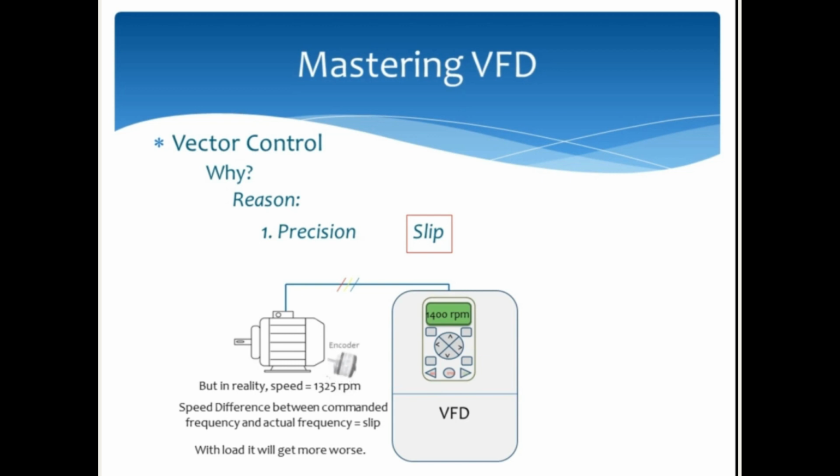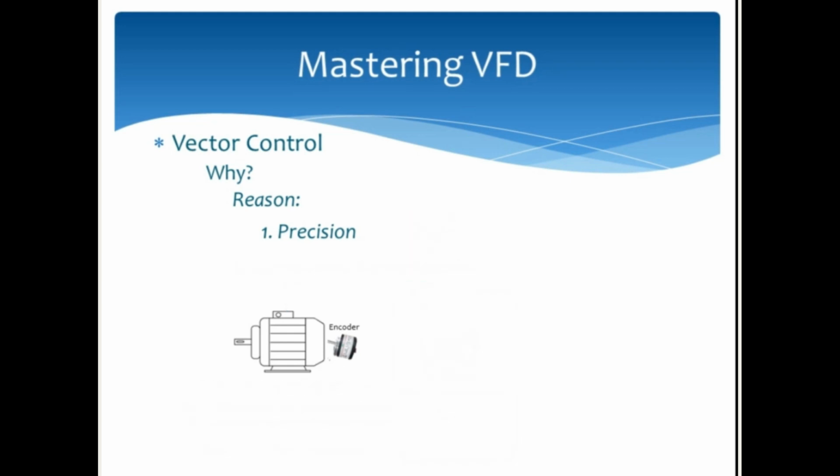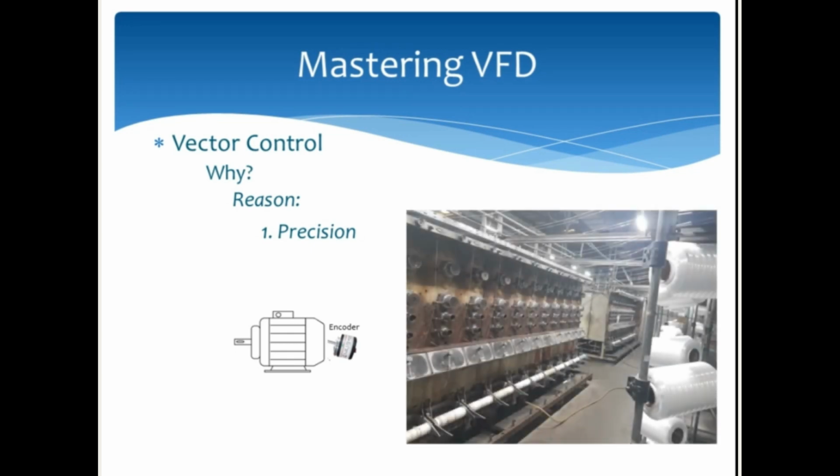With an encoder connected, the VFD can know the actual speed and compensate the speed difference by increasing or decreasing as required. So we get the precision. This is particularly important in elevators, which will help in getting the correct floor level. Also in textile, where if out of precision, speed can affect thread quality.